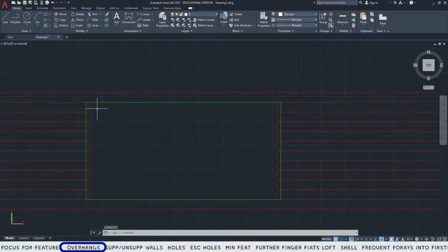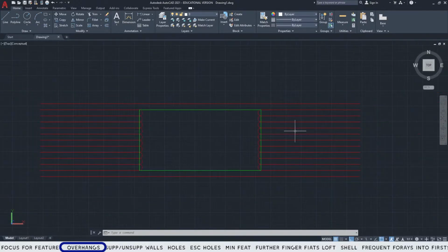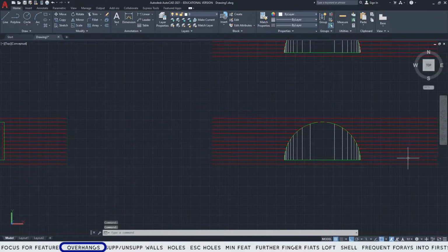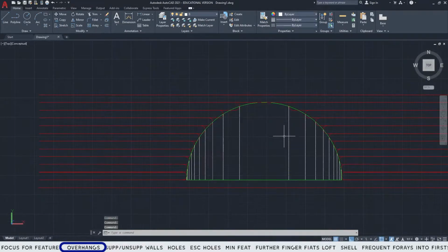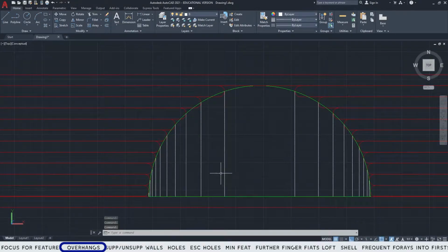What's going to happen in this case, as this top layer is printed and the print head moves across, is that the liquid plastic that comes out will have a tendency to sag across the middle because it has so far to stretch. So one of the things you can do is to change the shape of that, and you can turn it into an arch.